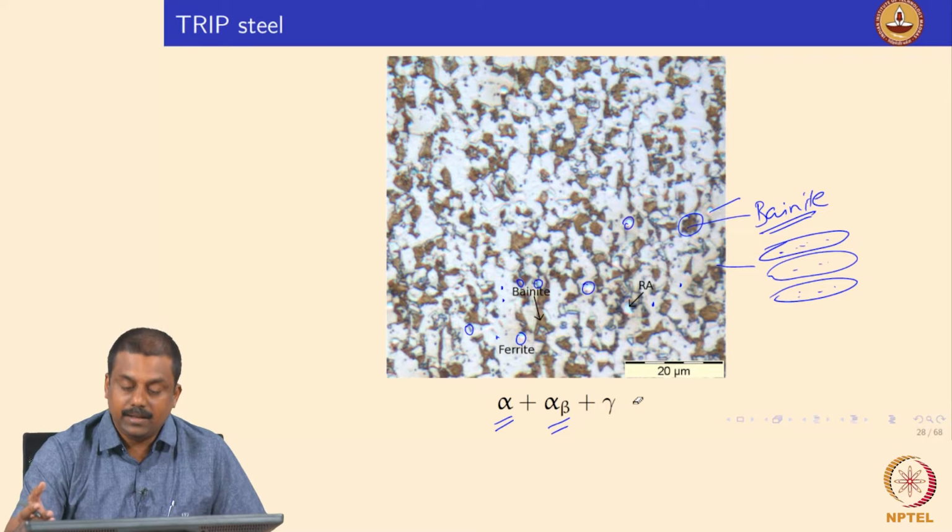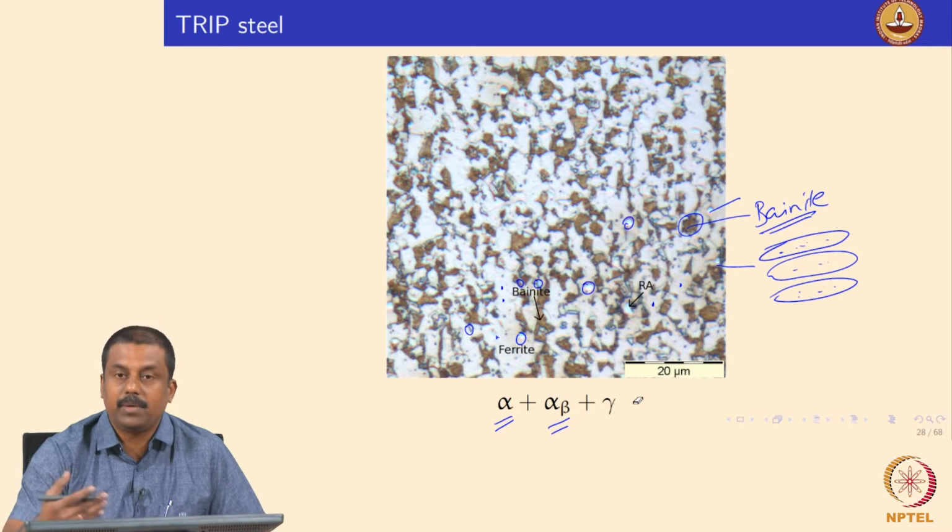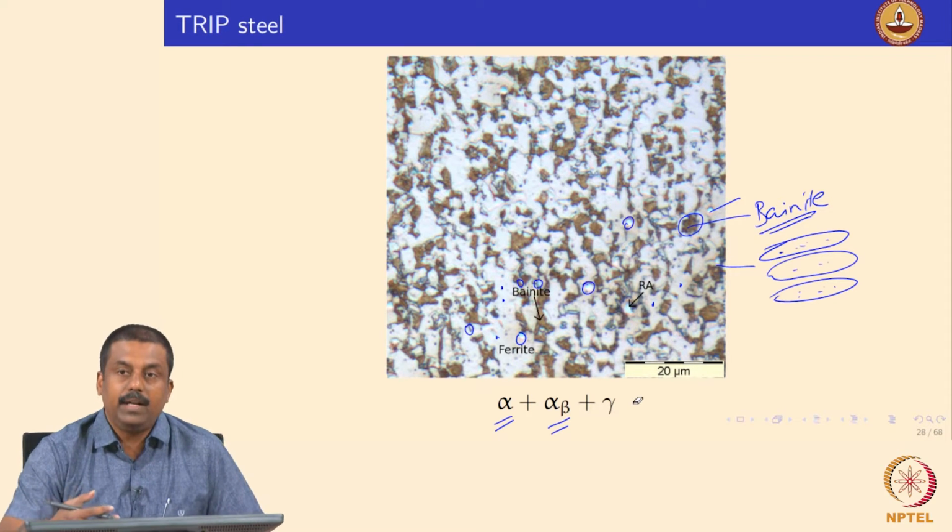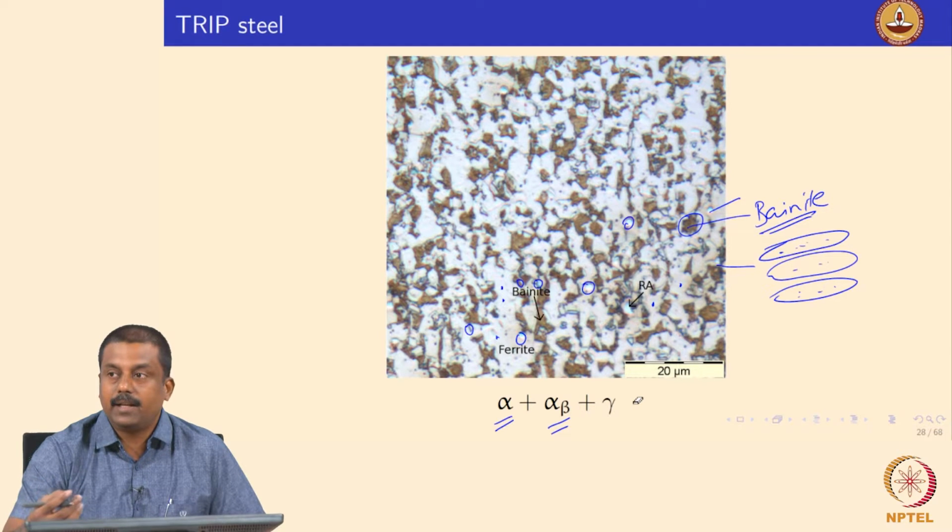So we gain advantage in terms of formability because when the austenite transforms to martensite by load, the mechanical energy coming from the deformation load is absorbed to transform the austenite to martensite. Thereby we increase the elongation significantly. And apart from that, by leaving retained austenite in the formed component, this retained austenite can transform to martensite while applying crash load. So the component becomes stronger